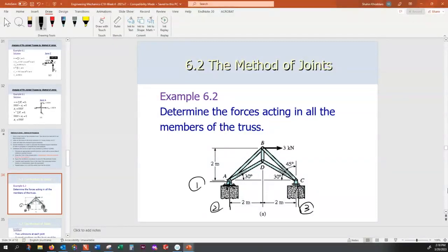This free body diagram is solvable. So once I solve that, at point C, I would only have two unknowns. So if I apply method of joint at C, I would get only two unknowns, this one being found from the previous stage. So this one is known, this is one unknown, two unknown, and method of joint can handle two unknowns. So that gives me the internal forces here.